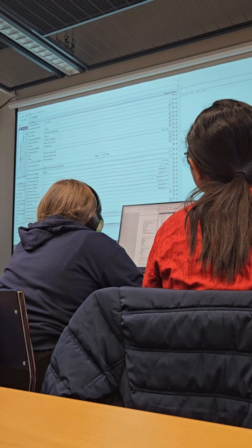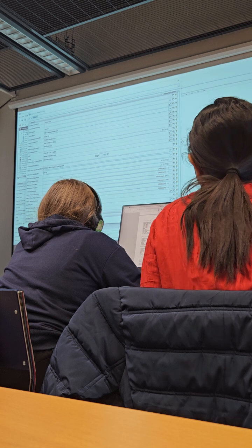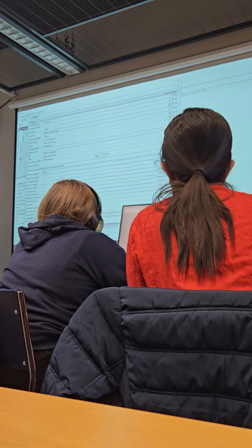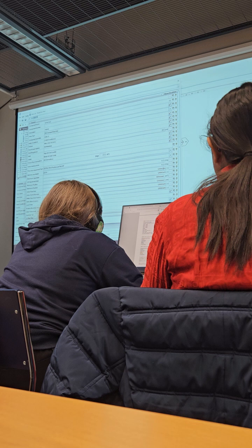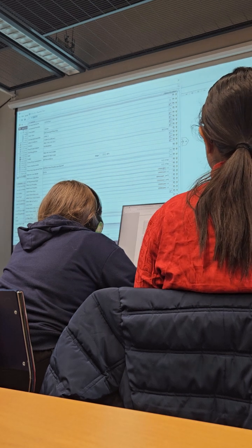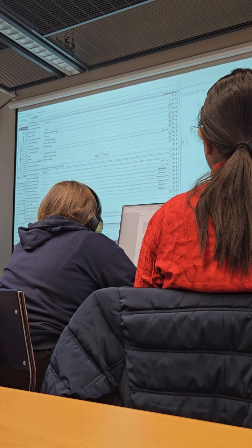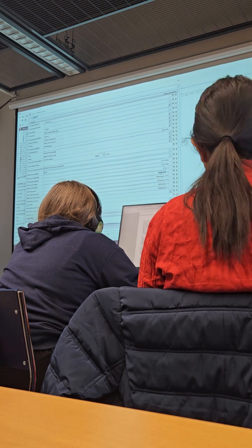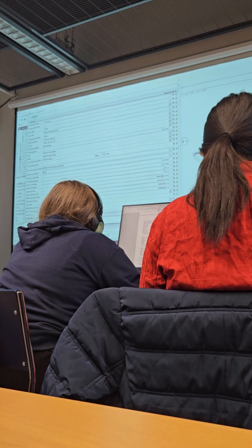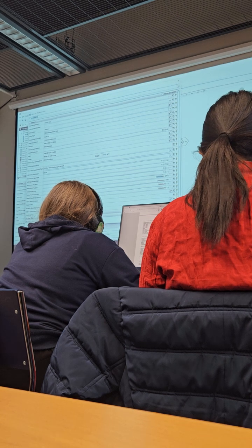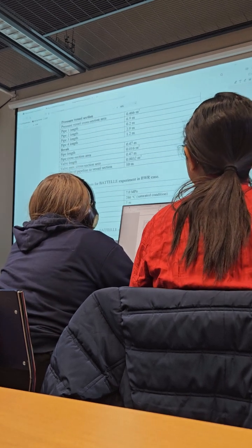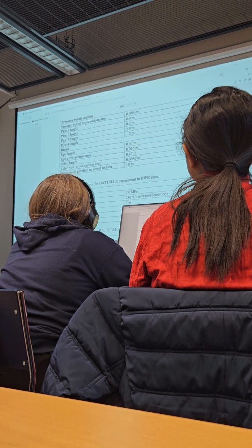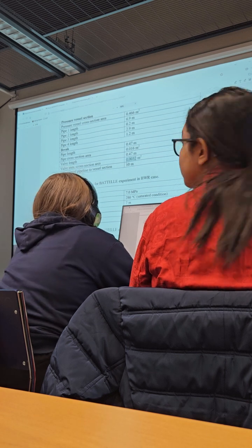It's just some values which we really don't use here, because we're giving the valve in such a way that we can change the option for the valve, but the minimum position is 0 and the maximum position is 1, and so on. And here we can introduce the valve flow area, which was given here in the instructions. So the valve flow area was 0.032.